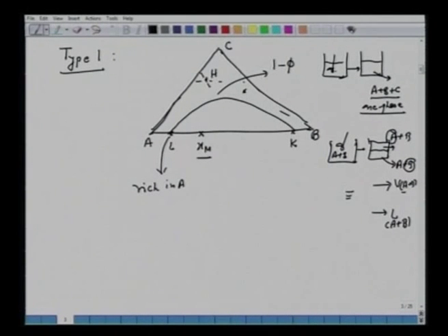This coordinate closer to B, it's rich in B. So we have 100% A, this apex 100% B here, and allow them to settle. Now we have this rich in. So this is nothing but a tie line. All right, this tie line is very close or very similar to this liquid vapor tie line.